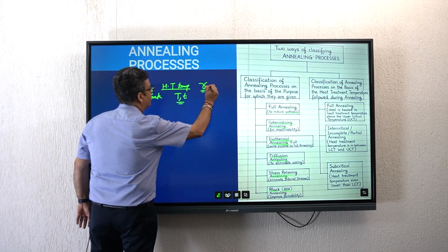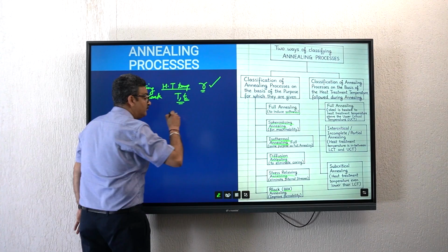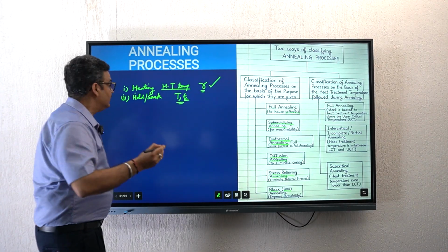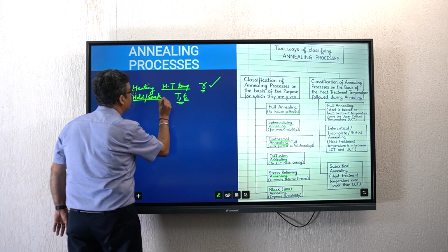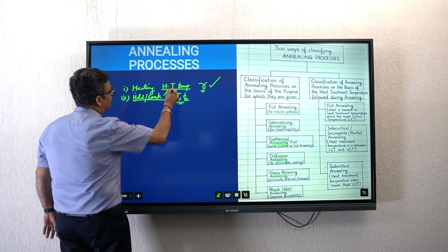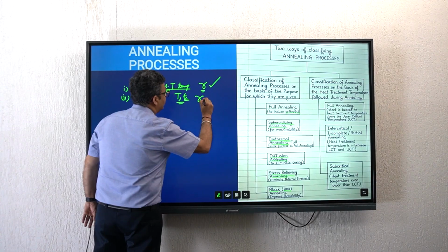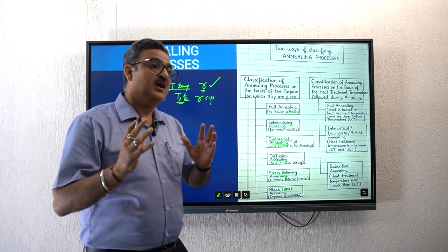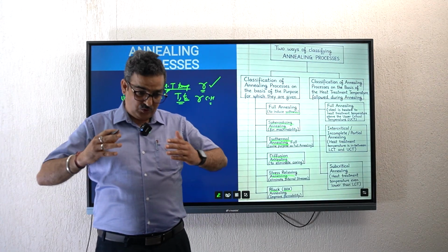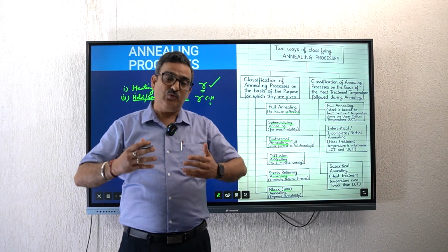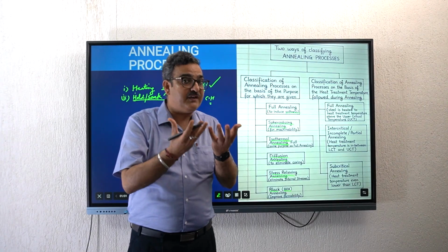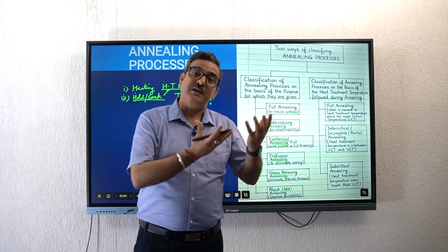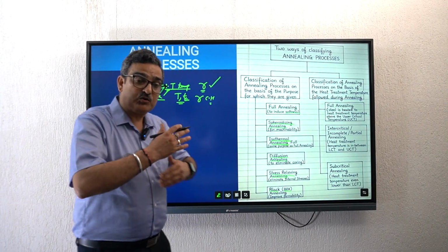So temperature you have already given in the first step, but diffusion needs more time at the high temperature to get completed. So you provide that holding or soaking at the heat treatment temperature, and diffusion gets completed, so this austenite becomes chemically homogeneous. Now you have that austenite with you, which is ready to get transformed, which is ready to get decomposed into the product phases which you wish to see in the final microstructure of the steel under room temperature conditions. So you will now cool your steel.